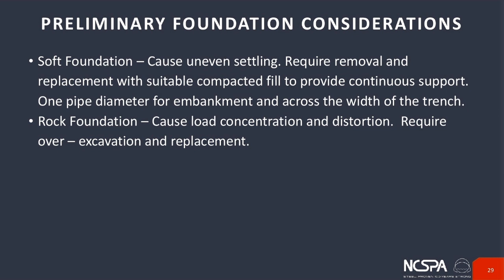Soft foundations will cause settling and uneven settling of the installation. So you really want to over excavate those foundations and replace them with good fill. And then rock foundations, they cause concentrated loads and distortions of the pipe because you get those hard places in the soil. Again, you want to over excavate that foundation and replace it. Down here where we are in Georgia, we will typically see a rock base on our foundations just so you have a good solid foundation to seat into so that you can begin your installation.